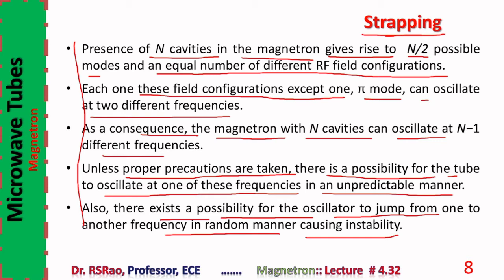This is one issue. Another issue is that the device may start functioning in the mode in which it is supposed to be in the beginning, but later it may jump into another mode and function at another frequency. This mode jumping can occur in an unpredictable, random manner.